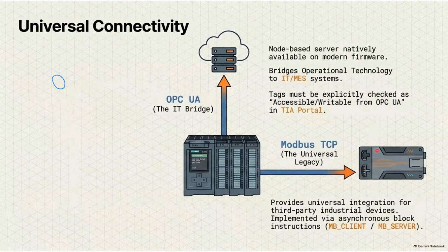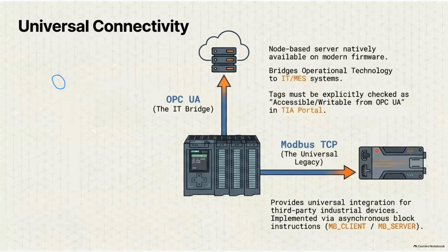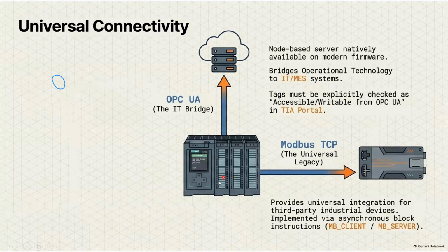In the interface module, we program the number of devices connected and their addresses. For each millisecond, or each tenth of a millisecond, the data from one particular device will be collected, and for that data, the address will be assigned and it will be fed to our main PLC. So Modbus communication happens in this way, whereas Profinet is straight away a different protocol.